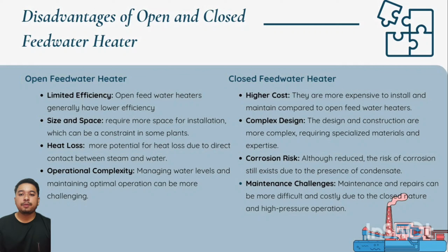Second is complex design. The design and construction of closed feed water heaters are more complex, requiring specialized materials and expertise. This can lead to higher engineering and construction costs. Third is corrosion risk. Although the risk of corrosion is reduced, it still exists due to the presence of condensates. Proper material and maintenance are required to minimize this risk. Lastly is maintenance challenges. Maintenance and repair can be more difficult and costly due to the closed nature and high pressure operation of these heaters. Accessing internal components for repairs can be a challenge.